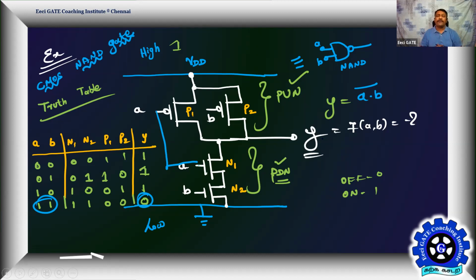Because in future we're going to build all the digital logic systems only by using these logic gates. Once you know the budget of a single logic gate, then by knowing how many such logic gates we are using, we can arrive at a similar budget in terms of CMOS. Instead of logic gate budget, you can go for CMOS budget. What's the cost of my design in terms of the number of CMOS transistors I need to realize such a digital logic design? That's why we implement everything only by using CMOS. So get that habit now itself. Even if you go to the VLSI level, digital system design will take you to that level only.